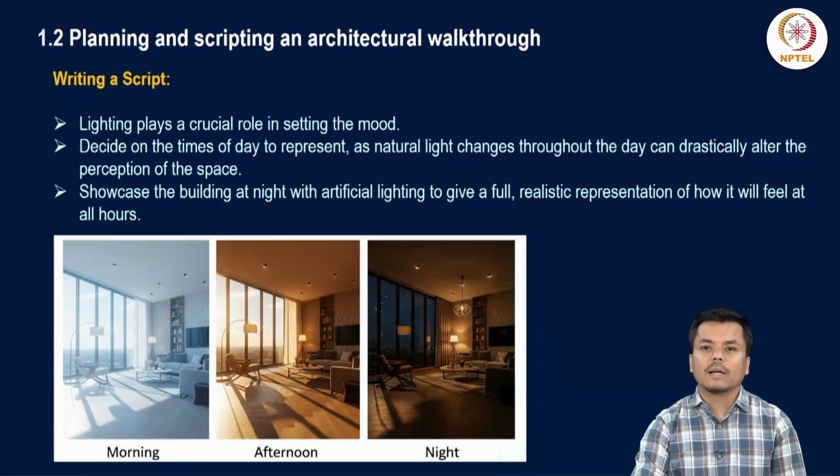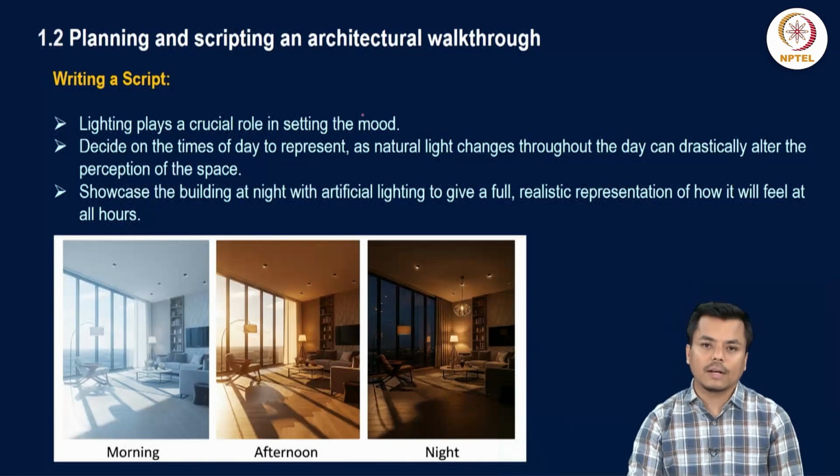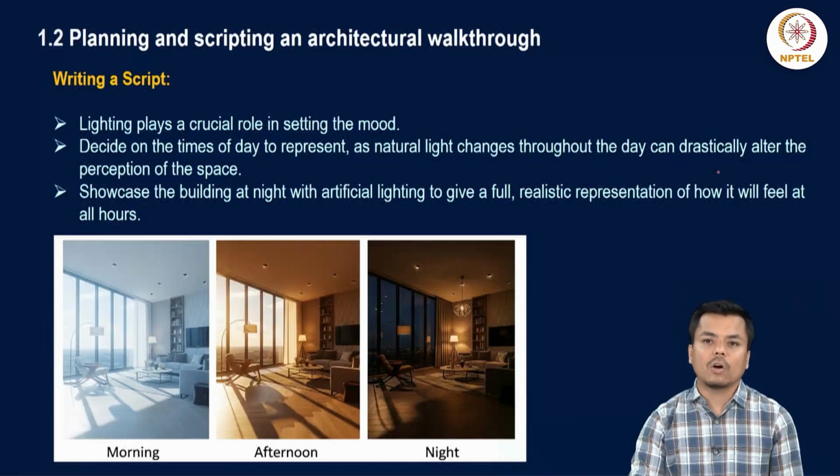When writing a script, lighting plays a crucial role in setting the mood, so it is very essential to focus on lighting. At what stage or time of day does this walkthrough represent? Based on that, the lighting conditions have to be adjusted accordingly. So decide on the time of day to represent, as natural light changes throughout the day and it can drastically alter the perception of the space. That has to be kept in mind.